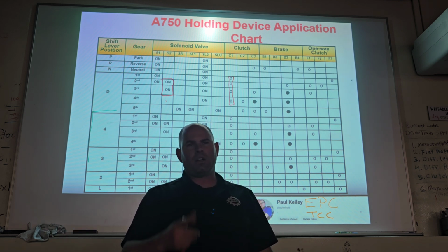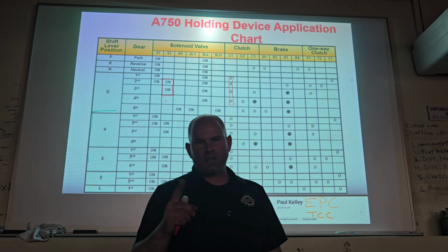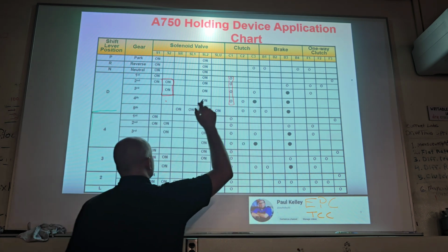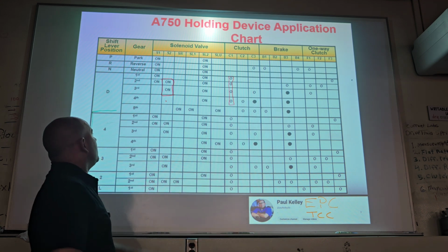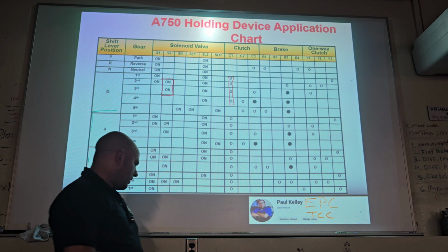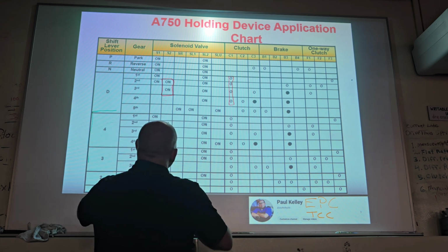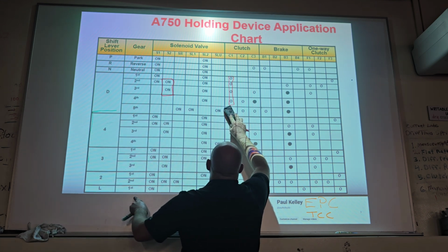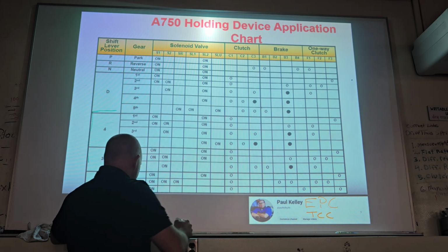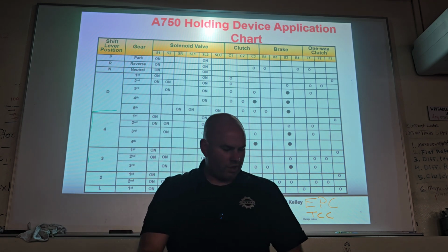Make sense? And on an electronically controlled transmission, forget about the governor. We're all about the shift solenoids. Check the shift solenoids, diagnose the shift solenoids. If the shift solenoid S2 is no good, that would make a lot of sense. Cool? Roberto, go ahead. Exactly.